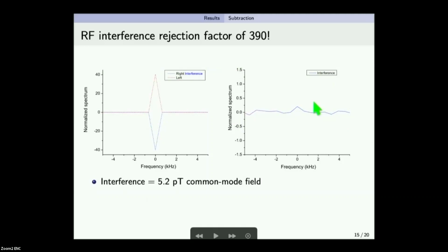So what happens if you put them both on at the same time? You can see that the signal from individual measurements is almost all interference. You would never be able to see the signal out of this, especially because we did it at the exact same resonance frequency at around 1 megahertz. So this is all interference, and there would be no way to tell.